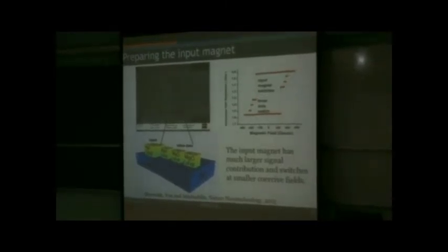What we see is that the energy dissipation, you can look at this as 3 inverters connected one next to the other. We are lower in energy dissipation compared to a high performance logic 3 inverter chain, but we are higher than subthreshold logic. Our speed is comparable to or slower than subthreshold logic.